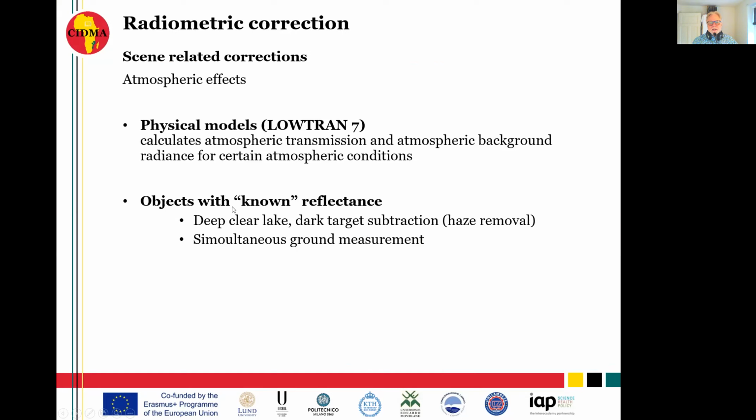If I find the lake and it has the same depth and should have the same temperature and things like that, actually, I can see the change of the pixel values. If the pixel values are slightly higher in one satellite image compared to the other one, we can think that the additional pixel values are related to haze or atmospheric properties.